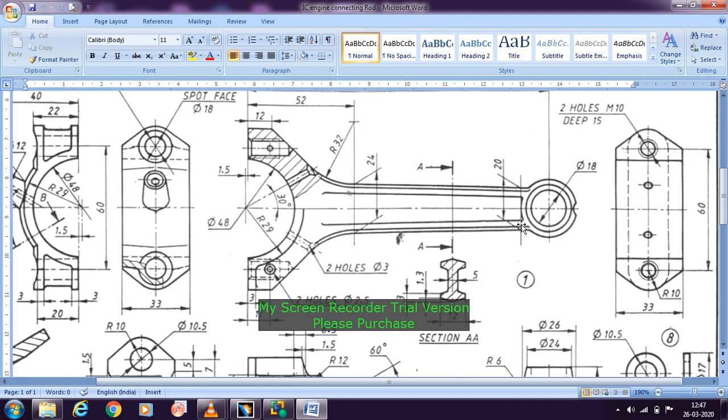Now in order to get the I section here, I need to see the dimension here. From the center the outermost dimension is for the radius 13, but when I take 13 here it will not be touching. So in order to be on the safer side, instead of taking the radius as 13, in order to create the plane I will be taking 14 mm here. I will tell you later. Even if I take the 14 mm, this I section will not be touching this object, so later we will be using the pad command in order to touch this object.